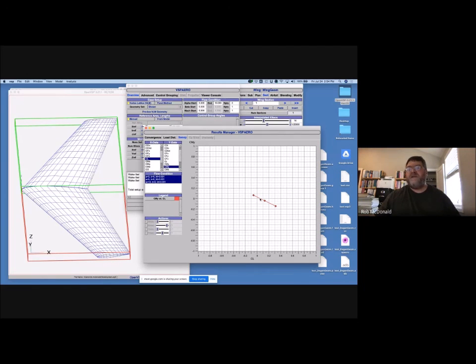In this case, it's very near to a CL of, I'd say, if this is 0.2, that's 0.1, that's 0.05. So very near to a CL of 0.05. That point, which isn't even one of the points we analyzed, but where this line crosses the horizontal axis, is where this airplane would trim. Okay, that is the point where moment is 0, and it's going to trim at that CL, that 0.05.